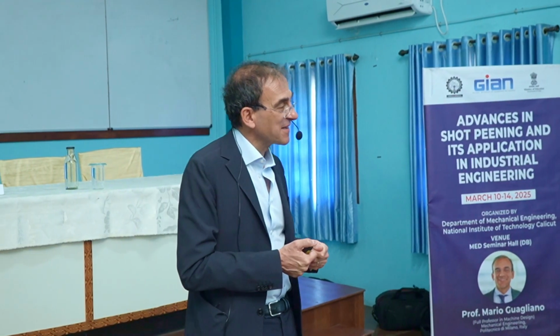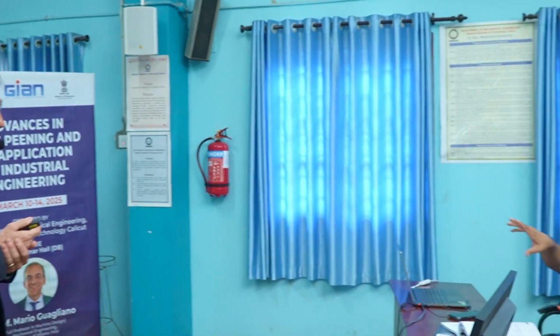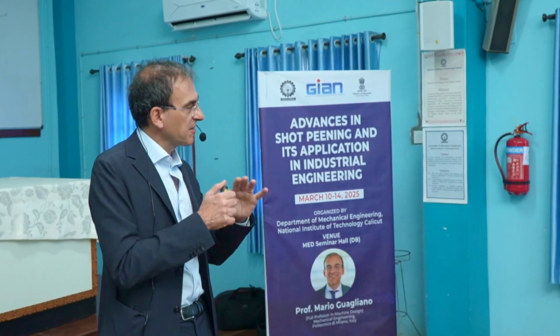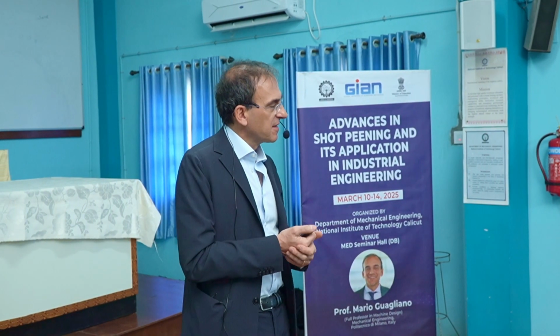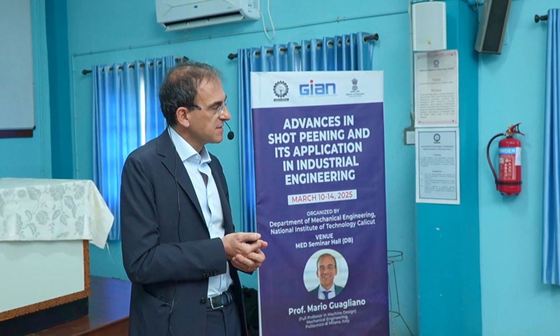So if all the conditions are the same, and due to some thermal treatment, say annealed steel is there and normal steel is there, and we are using the same processing parameters, the peening parameters are the same, then we will be getting two different depths of residual stress? If the mechanical properties of the materials are different, if you use the same parameters, same shot, same intensity, the result will be different, of course, yes. And so this will be affecting the fatigue life too?